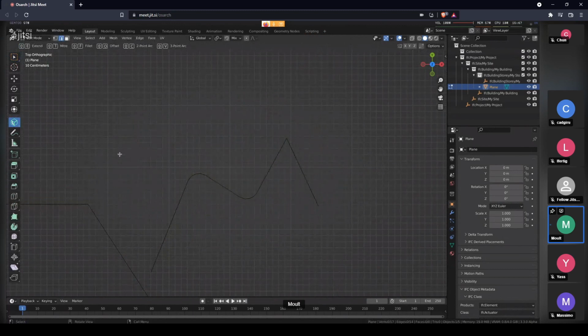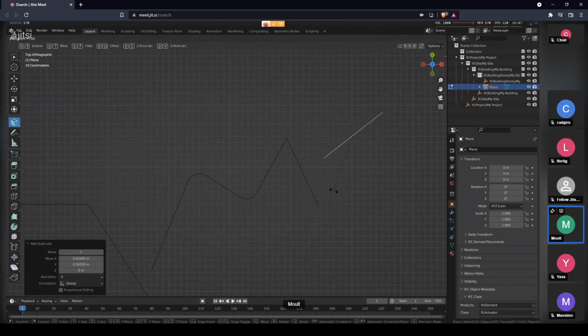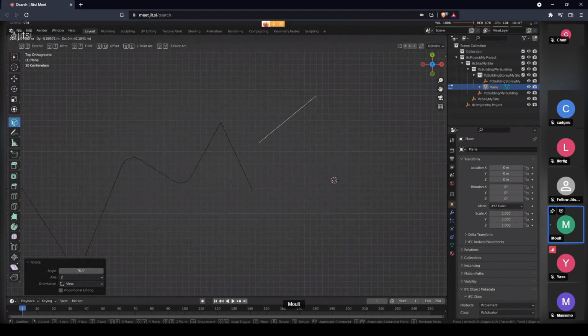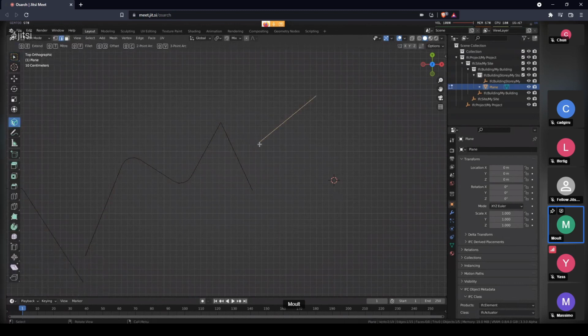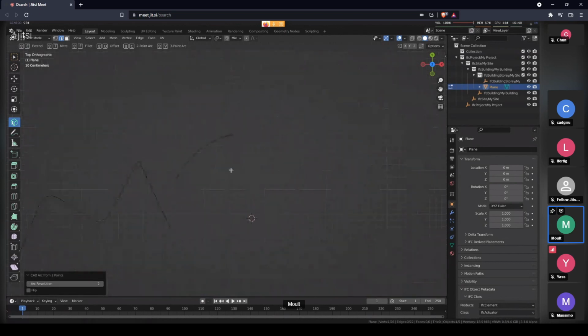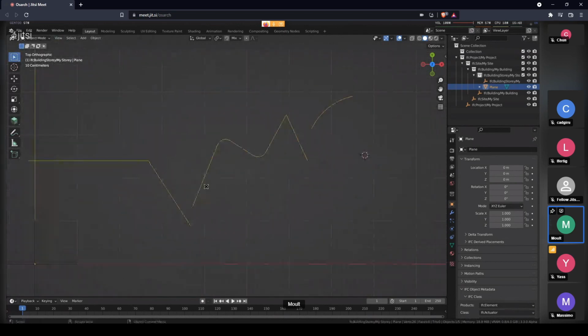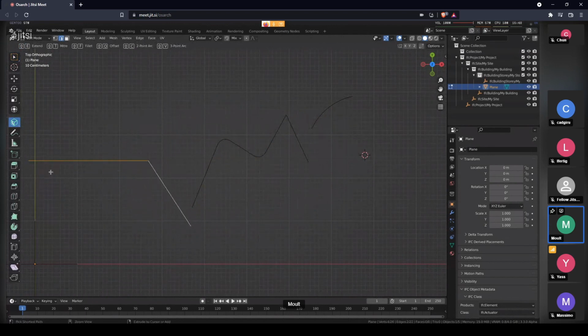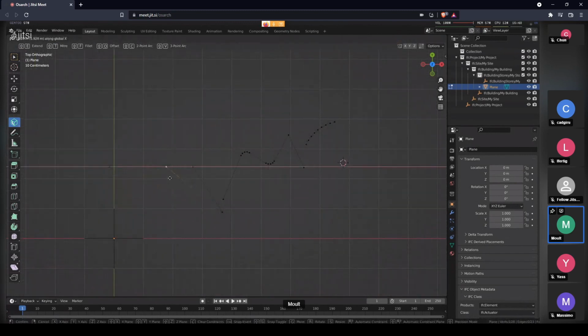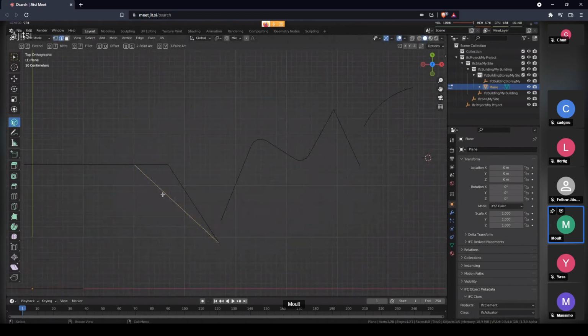I can also do a two-point arc, which I think from memory is you choose two points and a center line, and then I can do Shift C, which converts that into an arc. I can specify the arc resolution. So that's really good if you have this type of thing going on and you want to get this angle or this arc. You can convert it.